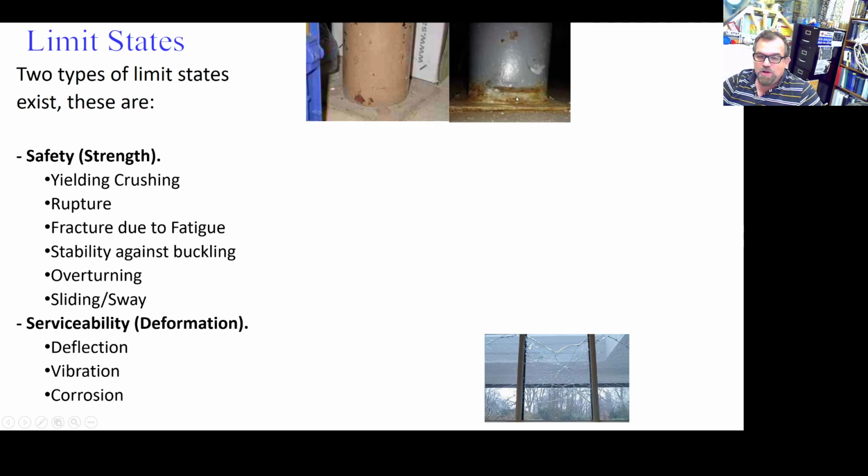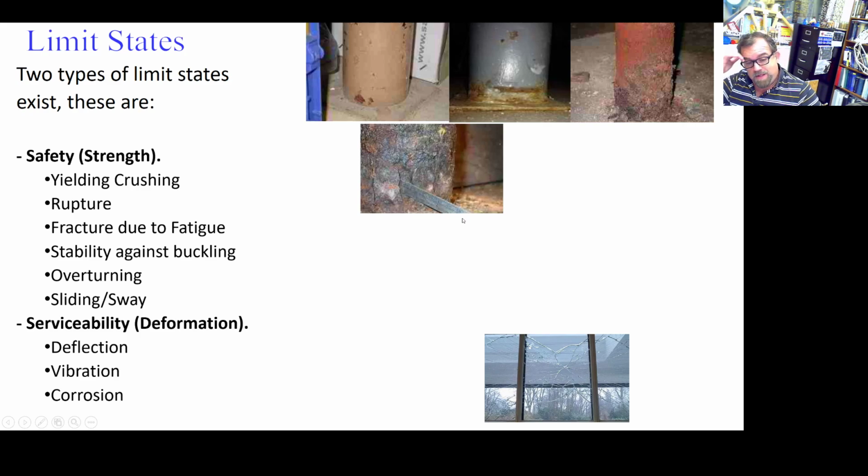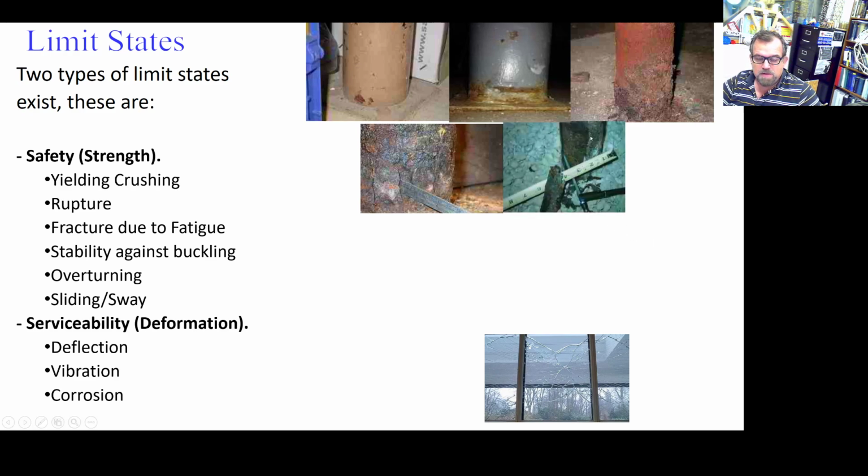0.01%? I don't know. What about this one? What about this progression? Same situation applies, right? What about this one? Oh, well, now we are a little bit different. We have a spall in there. What should I do? Take the column completely out, demolish the column and put the new one? I don't know. What about this one? It's falling in pieces. So there are different degrees of corrosion.